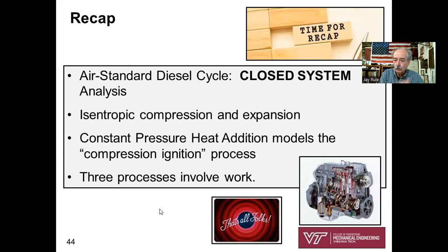Okay, so quick recap. Remember, for an air standard diesel cycle or the Otto cycle or other internal combustion engine models, you're doing a closed system analysis, not an open system. That's different. Open system analyses were for steam power plants and some others that are coming up. Closed system, internal combustion engines. Remember that the compression and expansion processes for these are considered isentropic: reversible and adiabatic.